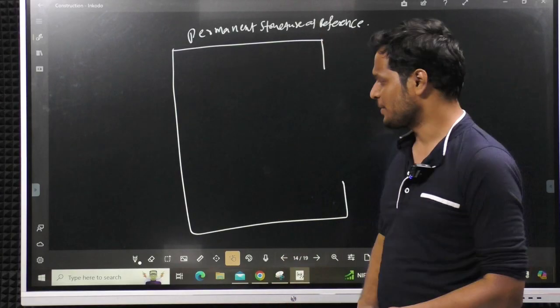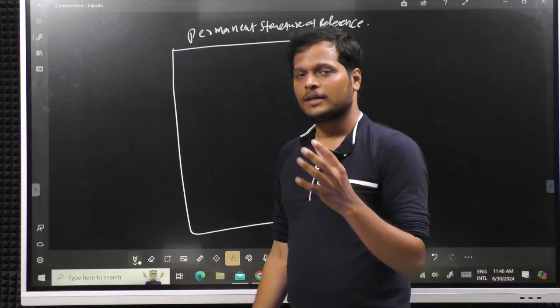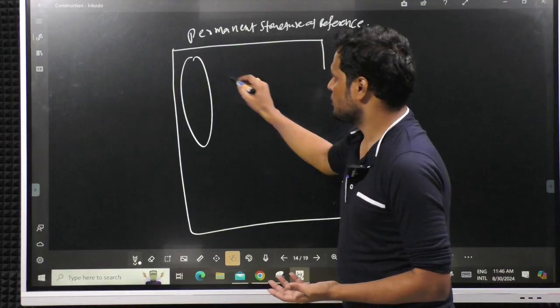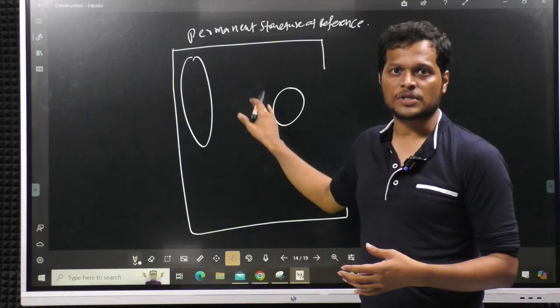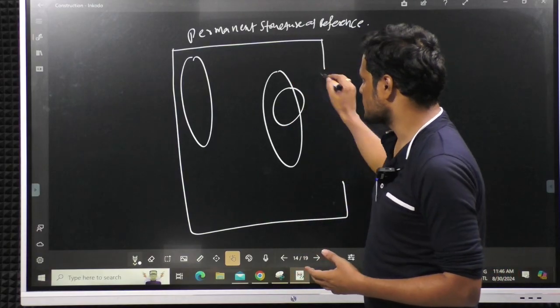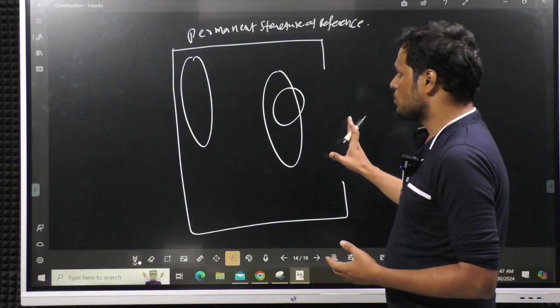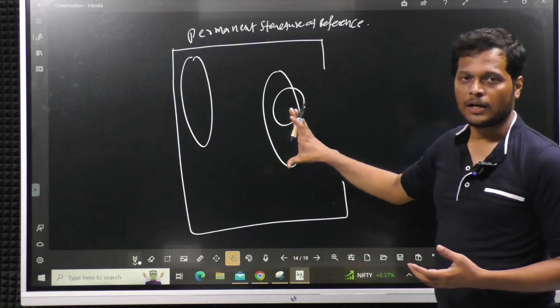Maybe most of you might know this: whatever structures you are planning, generally we will be working from outside to inside so that execution is smooth. If you construct the structure inside first, vehicle movement will be very difficult. So if this is the opening, I will construct here and come like this.